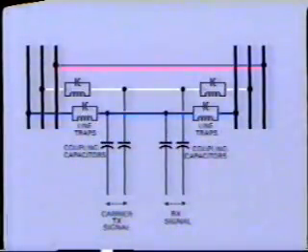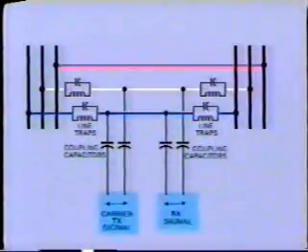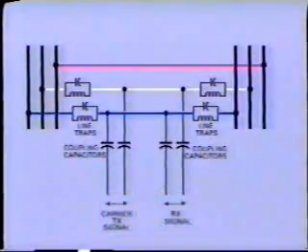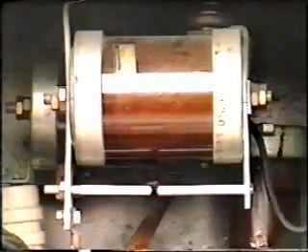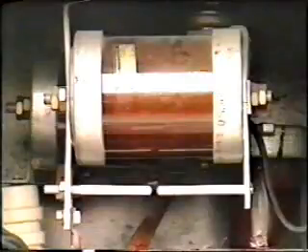An alternative scheme may use a phase-to-phase connection. As shown in this schematic, the transmitter and receiver are coupled to 2 power line conductors at each end. The carrier signal is applied line to line. With this arrangement, the requirement for line coupling equipment is doubled. Let's get back to our carrier accessories as they are known.